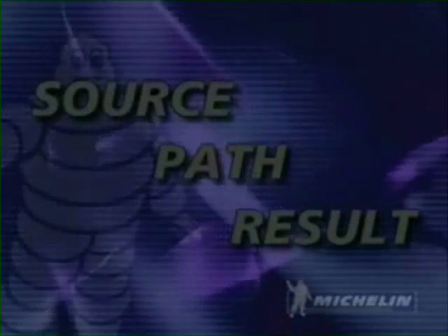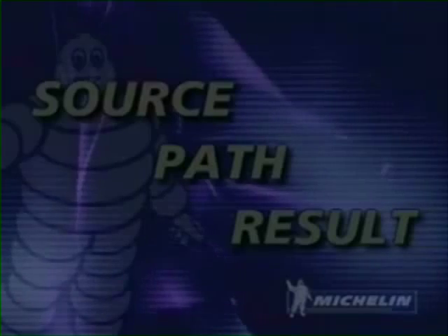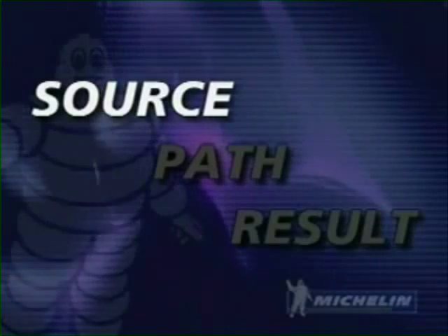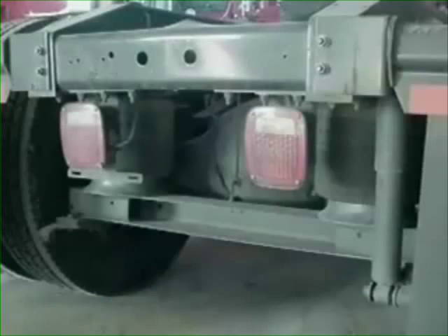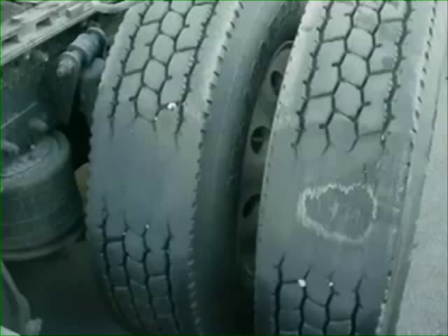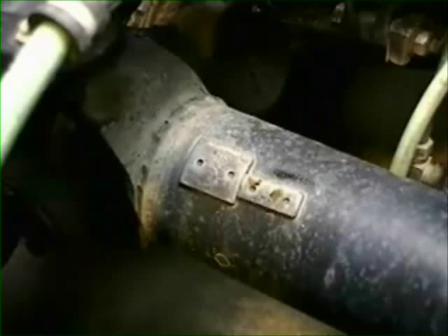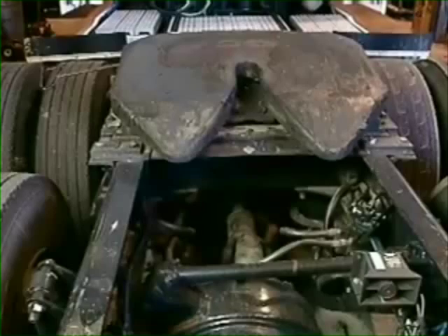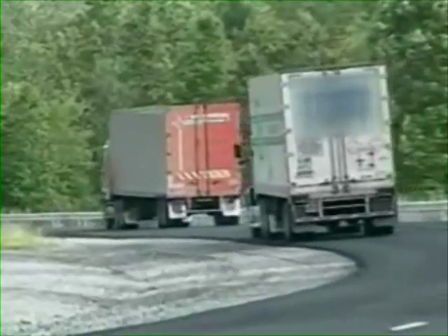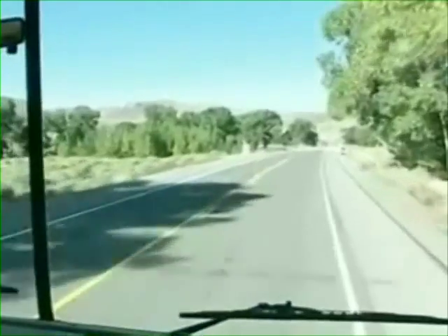Basically, a vibration complaint has 3 elements. The source of the excitation. The source can include a mismounted or out-of-balance tire and wheel assembly, an out-of-round brake drum, non-functioning suspension components, a flat-spotted tire, an unbalanced or misangled drive shaft, fifth wheel position, influence from the trailer, or road surface roughness.